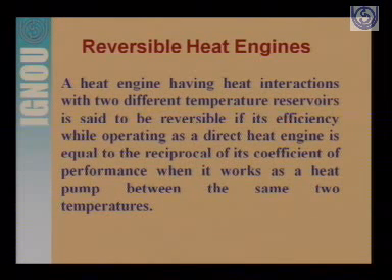Now, reversible heat engine. A heat engine having heat interactions with two different temperature reservoirs is said to be reversible if its efficiency while operating as a direct heat engine is equal to the reciprocal of its coefficient of performance when it works as a heat pump between the same two temperatures. We have got the expression for the efficiency of a direct heat engine, and for a reversible heat engine we have already got the expression for efficiency. We have also got the expression for the COP of a heat pump.